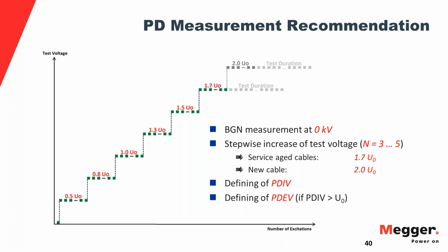And that is pretty much your minimum threshold, or your floor that you cannot go below. If you have a condition that is below the background noise, no chance of finding that in the field, because that's the nature of field testing. You have background noise. And then you start at a certain voltage, and you, in steps, increase that, not too many measurements, not too few.